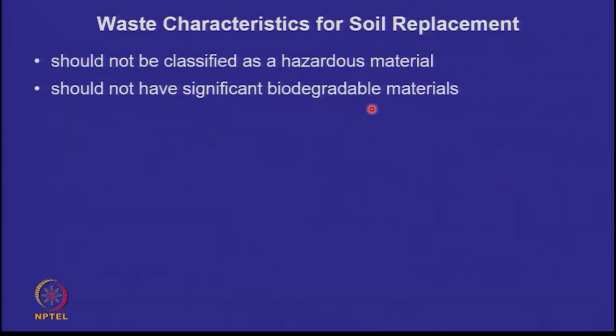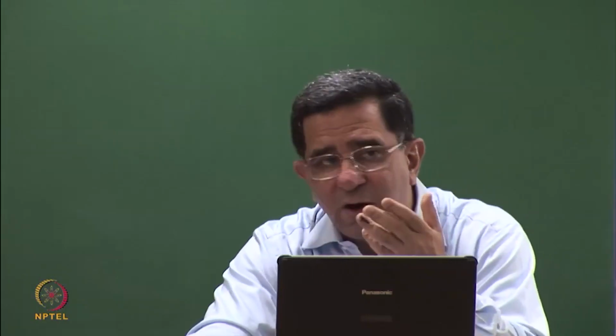But if you have 10-15% biodegradable material, be prepared that it will settle with time, and it is not due to consolidation, it will be secondary or creep kind of behavior.